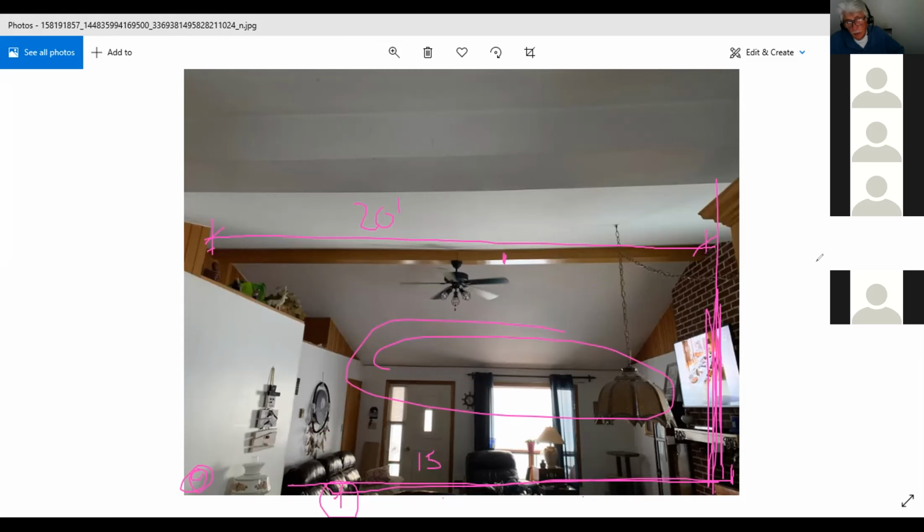Okay. And from there, I'm glad you got this picture, because this picture tells me a lot, you understand? It tells me there's nothing on the roof coming down in this area here. So all I have to worry about is the loads of the floor here, and these partitions here, you understand? Yeah. So that's something that we'll be able to calculate very easily. And like I said, if you only want to modify this column, and it's away from this end here, I don't care, because we're not going to touch this part of the structure. So all I have to do is add the weight of these two partitions in my calculation. You understand? Yeah. That's it.